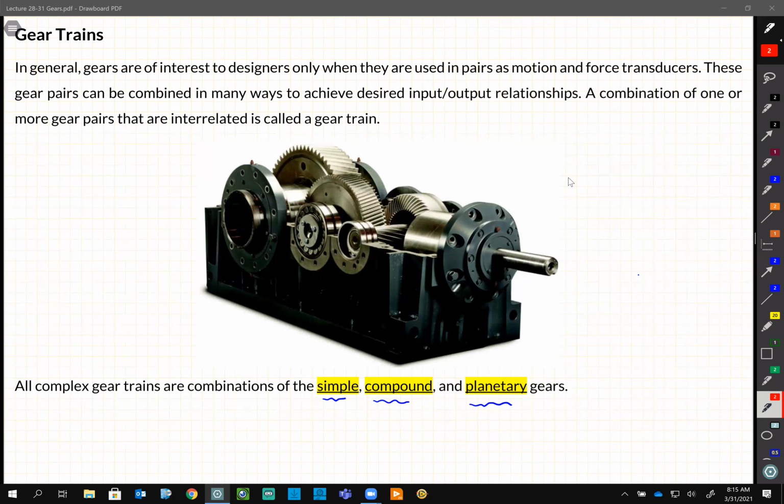And when I say $500,000, that is for the whole setup, because for metal printing, you need the printer, and you need the washing center to remove the chemical, and then you need the sintering. Because remember, for metal, after being printed, you need to put them in an oven so the particles get close to the melting point and sinter together. So you get that rigid metal part that you want.